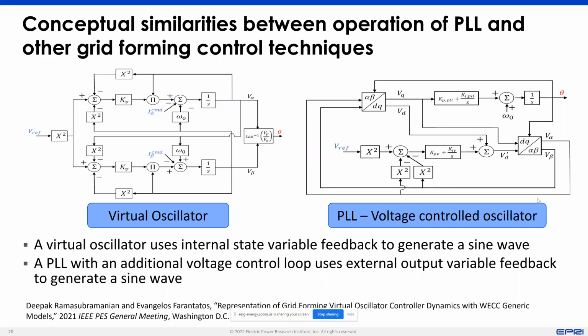So now let's look at it conceptually. As I'd mentioned before, and I promise you this is probably 1 out of 2 slides that have block diagrams. There's no other slide that has this kind of diagrams in this tutorial. But it's important, wherein you look at it from 2 perspectives. So you have a virtual oscillator, which as Wenzong showed is more of a nonlinear time domain based grid forming inverter.